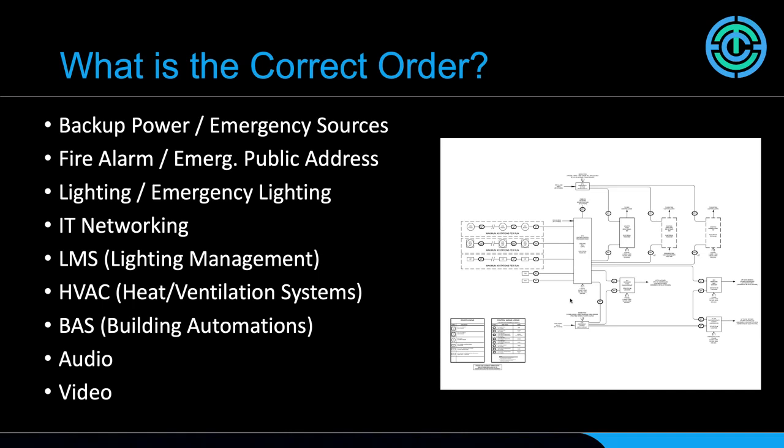But at the same time, those input sources can be used as reference for the HVAC system. If there's occupancy in a room, we can tell the HVAC systems that we need to turn on the air handling, whether it be cooling or heating. Whether the daylight is up or down, we can again give that information to the HVAC systems. Many of the ETC systems out there are not only lighting systems, but they're power control systems. We actually have the ability to do temperature control and other automations when it comes to that type of thing.